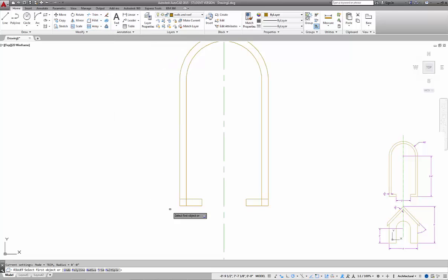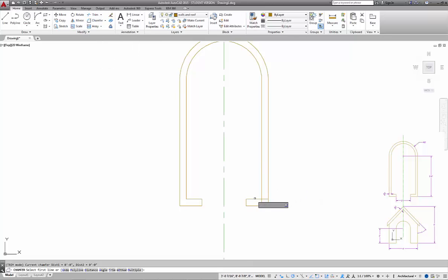So if I pick fillet and pick a surface that I want to keep, you can see what's happening here is that it shows me what's going to get grayed out, there towards the bottom, those two little lines. And it cleans up the corner. Just to prove it to you, I'm going to choose chamfer on the next one and do the exact same thing. I'll pick it in the opposite direction. So we pick the line where I want to keep it, pick the line where I want to keep it. Notice how it shows me the blue lines, which are going to be what my final drawing is, and it trims it up. So as long as the values are 0, you're okay. Everything works well.